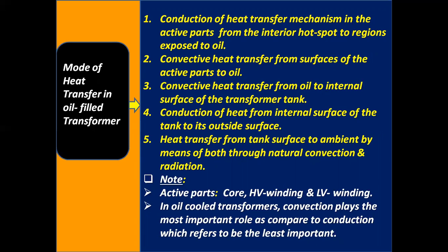Number 3, convective heat transfer from oil to internal surface of the transformer tank. Number 4, conduction of heat from internal surface of the tank to its outside surface. Number 5, heat transfer from tank surface to ambient by means of both natural convection and radiation.